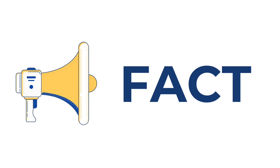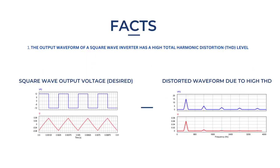First up will be the facts or problem statement. The output waveform of a square wave inverter has a high total harmonic distortion, or high THD level. The THD refers to the unwanted harmonic frequencies in the waveform itself. So this will spark some of the problems that I will mention now. The high THD level results in the waveform losing its characteristic square shape. It becomes more irregular with rounded edges and jagged peaks as the harmonics introduce additional variations to the waveform.